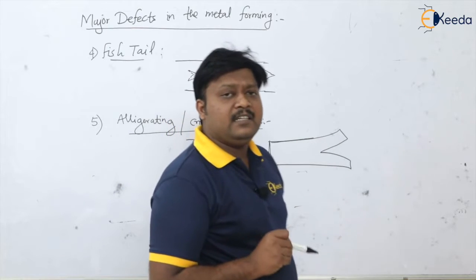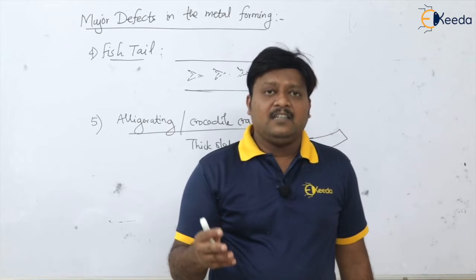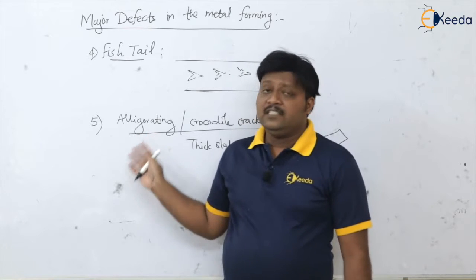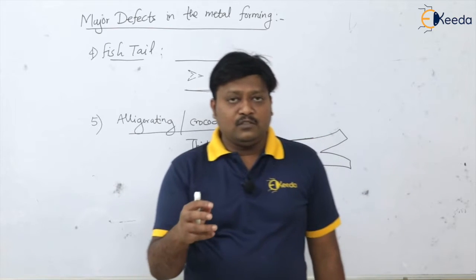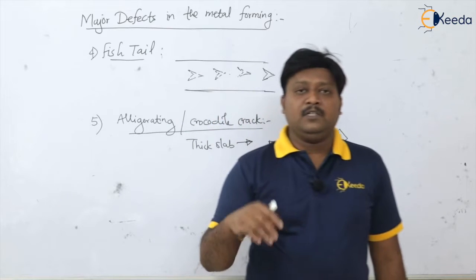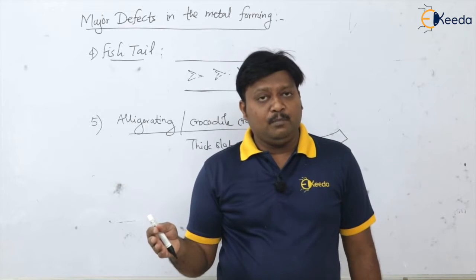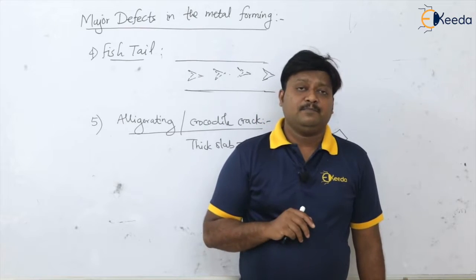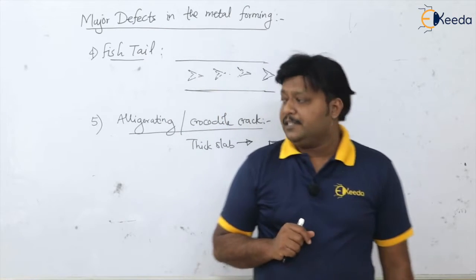Again, there are defects due to the irregular surface, then the scale or oxide layer present on the surface of the rolling sheets. These are actually the inclusions we can say. These are the sources of the defects which get generated in the rolling operation. One important defect, anisotropy in the rolling operation, is caused because of this scale which is present on the surface. These are the sources of defects in the rolling operation.